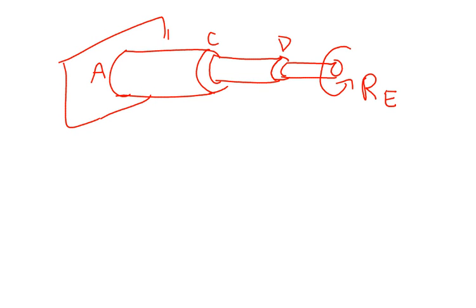Okay, so if you look, this is statically determinate, where the reaction at A is simply RE, negative. All right, so if the reaction at A is negative, and you make a cut at AC, and then CD and DE, then all your internal torques are positive RE.